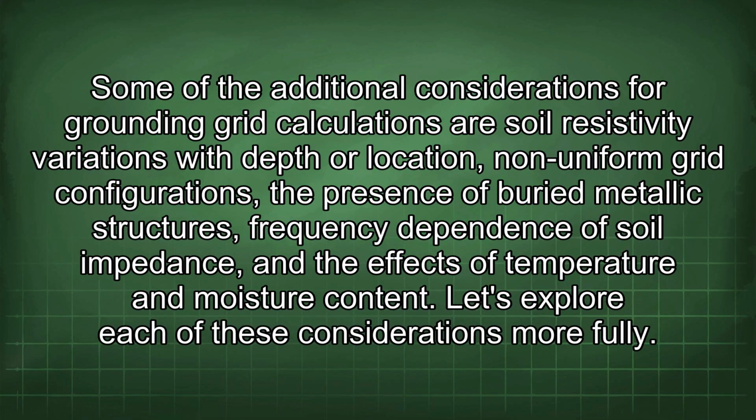Some of the additional considerations for grounding grid calculations are soil resistivity variations with depth or location, non-uniform grid configurations, the presence of buried metallic structures, frequency dependence of soil impedance, and the effects of temperature and moisture content. Let's explore each of these considerations more fully.